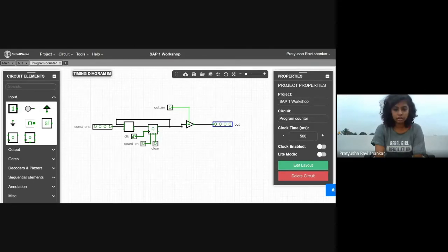So after you have reached 15, how does it set back to 0? If you add 1 after 15, it's basically going to overflow and set back to 0. Or in simple words, 1 plus 1 is 0, right? And that 1 gets carried over. So everything here becomes 0, and that carry bit, or the overflow, just gets discarded. So that's how it works here.